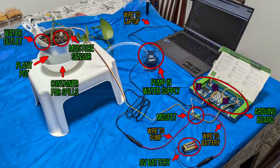Here is my setup. The USB connector to the laptop is used to initiate the Arduino board. Two cables were attached to the Arduino board, one connected with the moisture sensor and another connected to the MOSFET at A0 and D2 respectively. The moisture sensor was placed in the soil. The data from the moisture sensor determines the activity of the water pump. It also sends the data over to the laptop with the help of the connected USB.